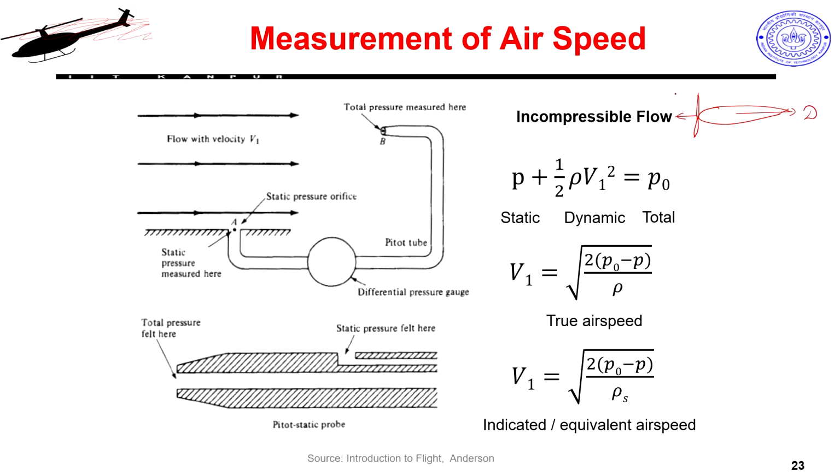This propeller must generate some thrust to overcome my drag, and this drag is a function of velocity, half rho V infinity square C D S. Even if C D is constant or increasing with angle, overall at higher speeds my drag will increase.